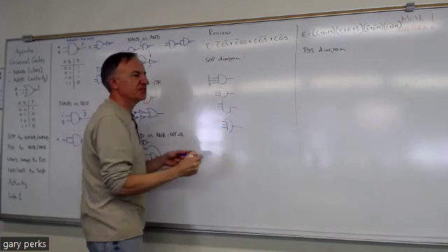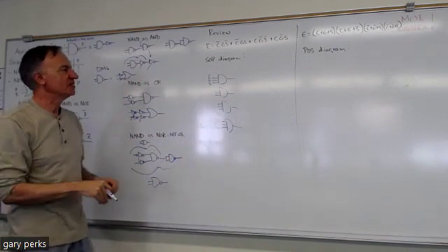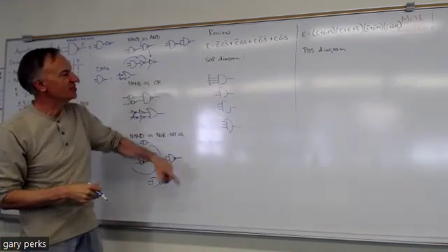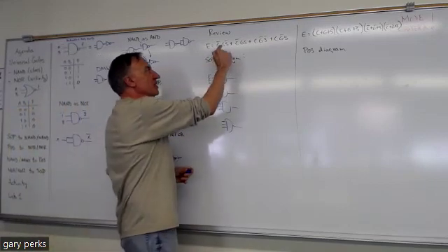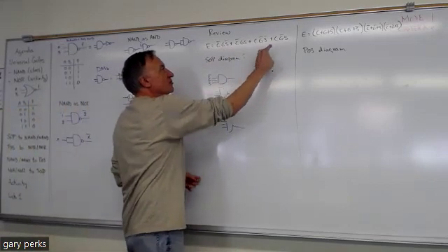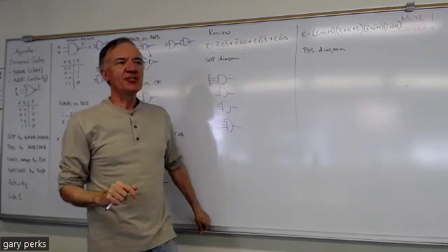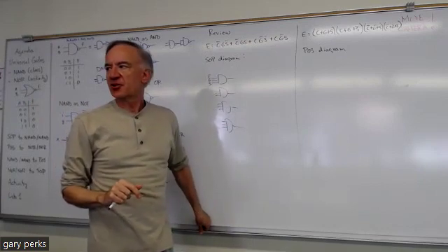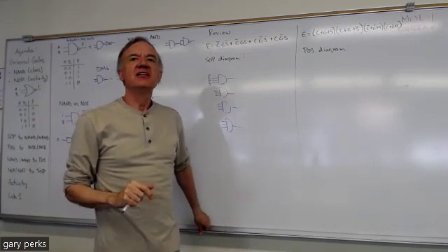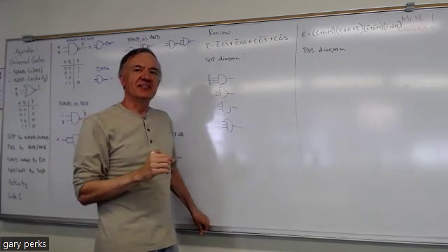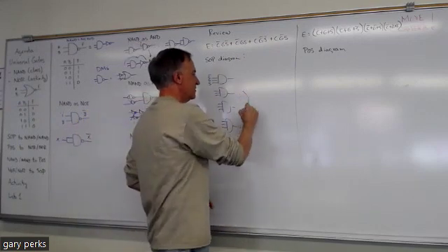If you look back in your notes, we did that previously. So I'm not going to write in all the variables here, but you can do that. It's going to take an AND gate for each term. And then how do we OR all the terms together? What kind of gate? Just a single OR gate, right?